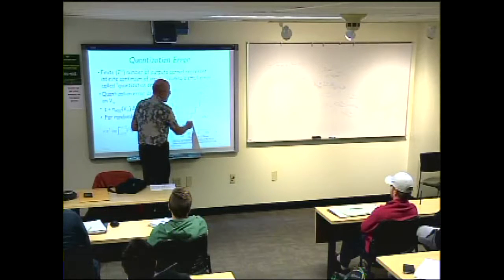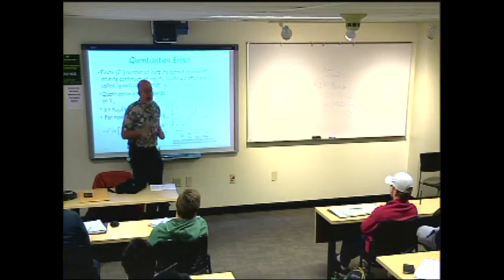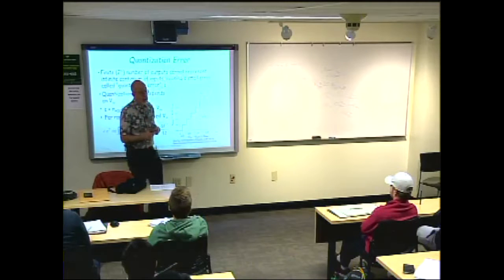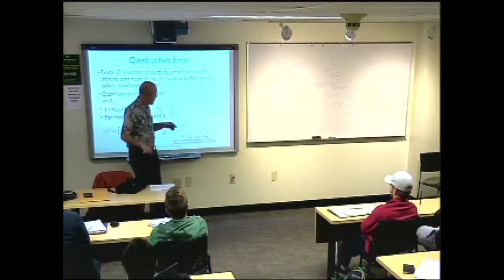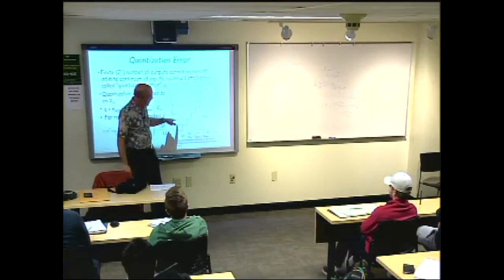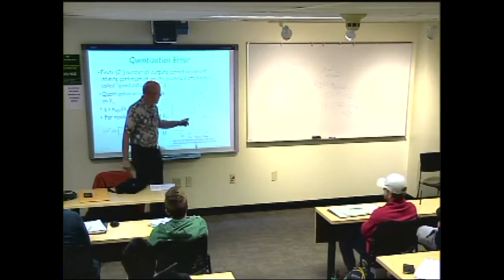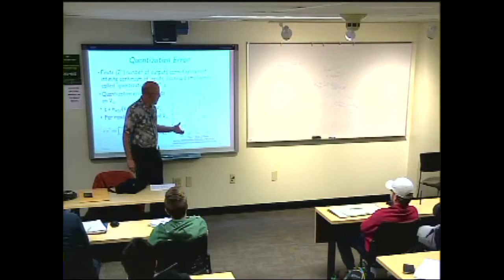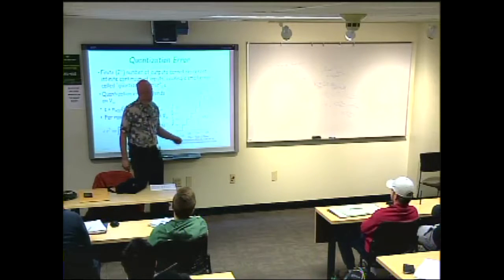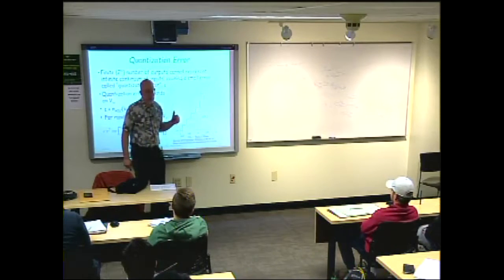Then sometimes it would be on this step up here, and sometimes on this step down here, and I could average those two steps in time, saying, okay, it's bouncing back and forth between two different readings, between a voltage of 2 and a voltage of 3, so I'm going to just average those. And it would spend more time on 2 than on 3. If I average those, then I can find out more accurately what the value is than if I was just believing just this level or just this level.